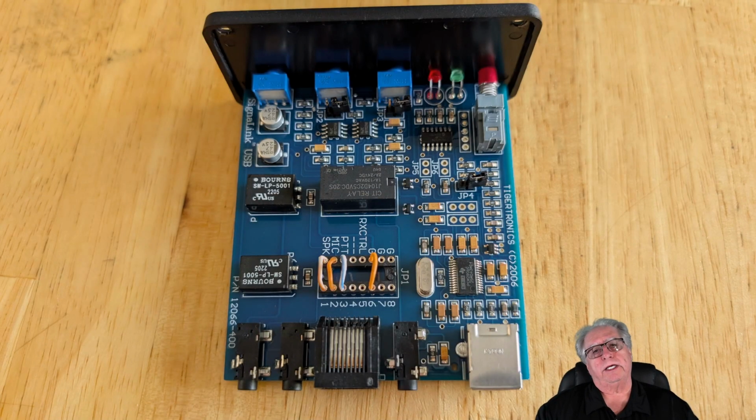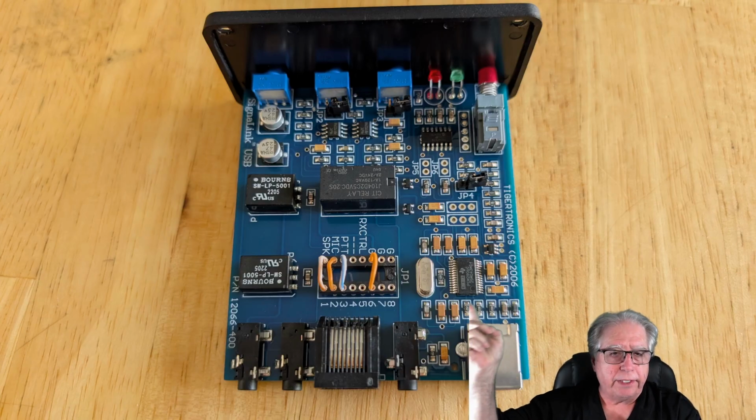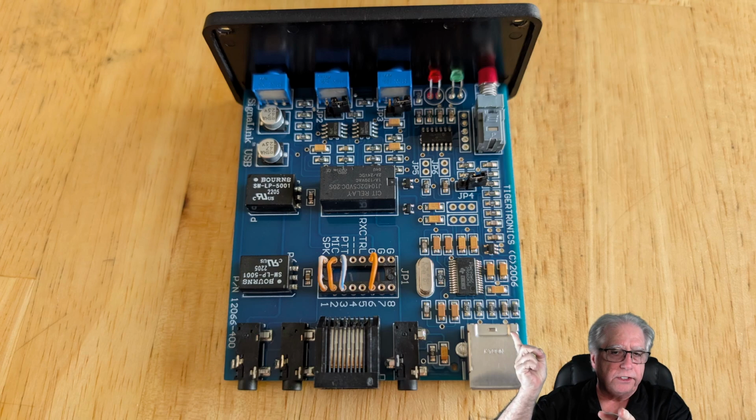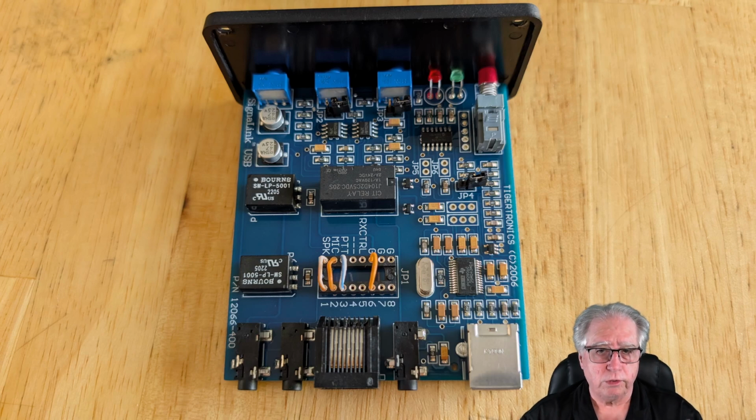Now, inside the SignalLink, if you look right, wrong hand, if you look right, there we go. I got to bend a little. You look right there, you're going to see 4 wires, right? White orange, orange, and then I've got a white blue, and then there's another solid orange. But what those wires do is it takes the input and output, which is written there, push to talk, mic, speaker, and ground, and it puts them on different pins on the RJ45, and the numbers there list those pins.